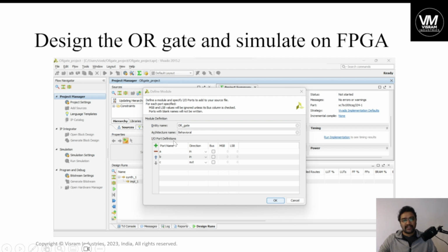When you go for standard cell custom layout designs, nano cell designs, where you will actually design the AND gate cell at the micro level, at that time you need to mention pins, because only standard cells have pins; they can't have ports, a port is a group of pins. It's not declared anywhere in the textbooks, but it is taken as a standard in the industry.